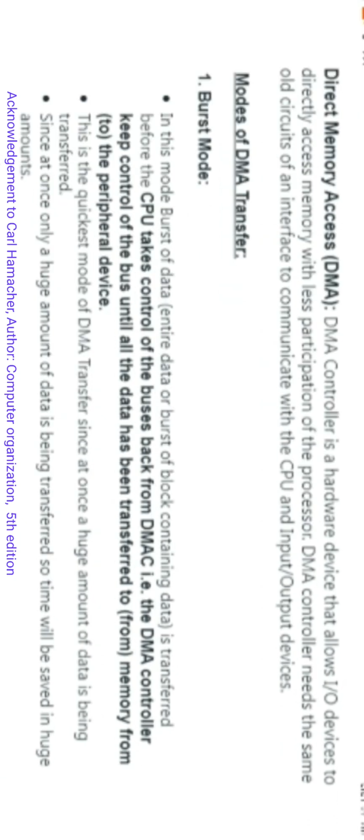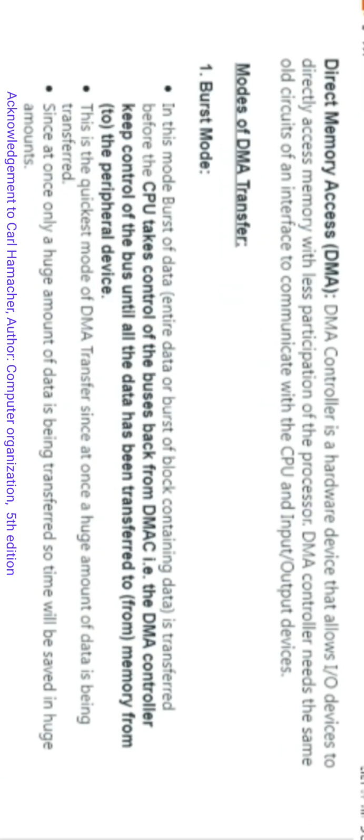But the processor initiates the transfer and gives permission to the DMA controller, which transfers the whole block of data, and after completion informs the processor through an interrupt request bit. Then the processor comes to know that the data transfer operation is over and takes back control over the system bus.